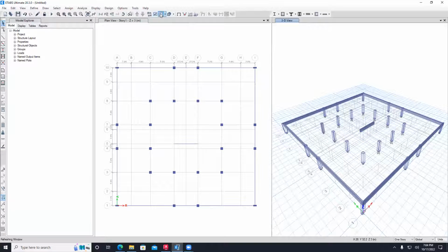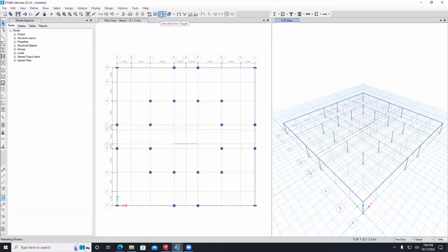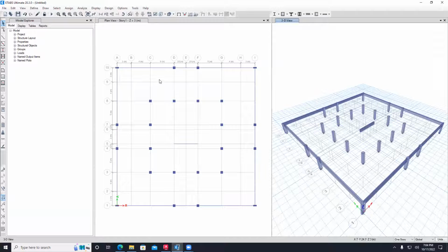So, yep, here we go. So we can draw the walls next. Actually, the walls you can also draw, same thing like what we did with columns. Can you see what happened here? If I click on the 3D, these will be deactivated, but if I click on 2D, these sections will be activated again.